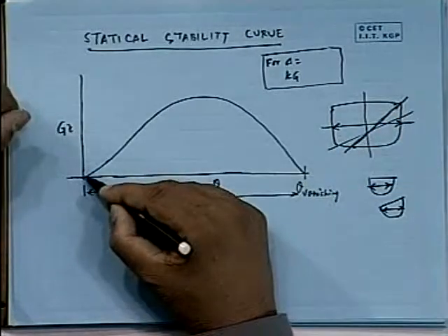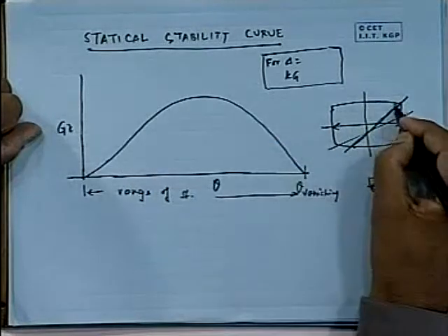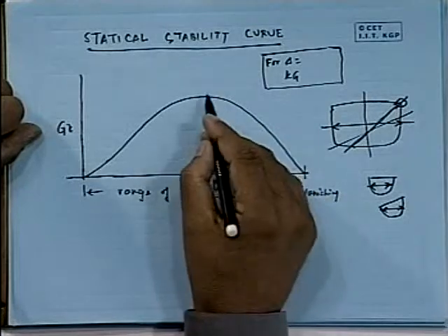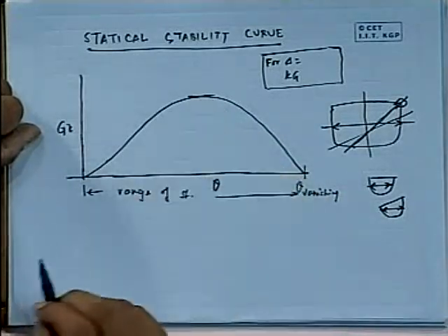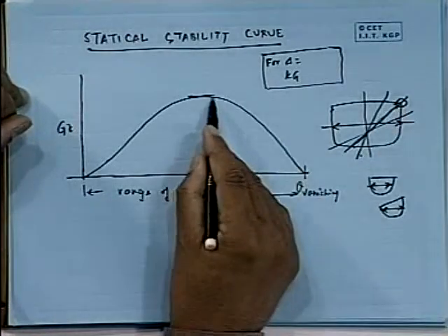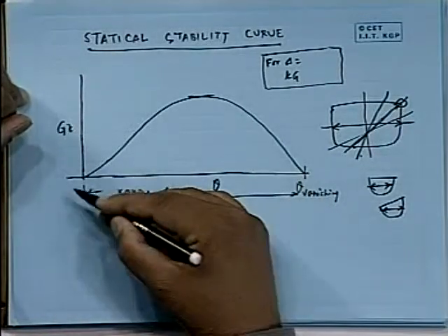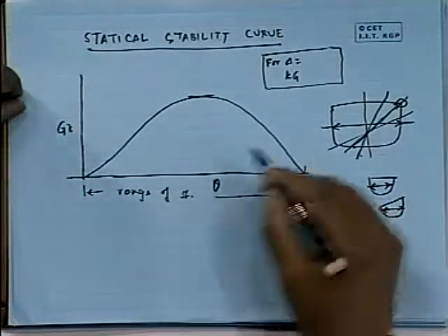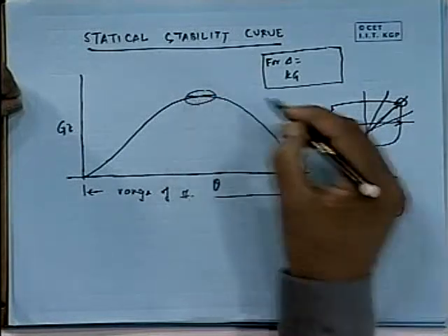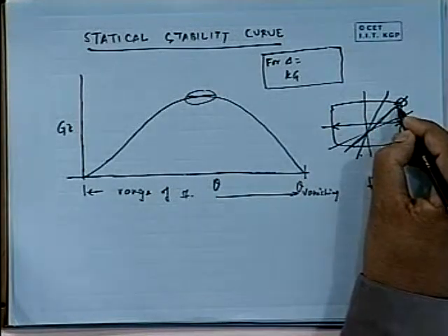That is why the GZ curve normally increases. But then there is a point where the deck edge gets immersed. Normally that happens when this reaches maximum. After that, it begins to come down. This is exactly how most ships behave. It is not exactly that the maximum corresponds to this, but roughly it will always be around that, within 5 degrees definitely.